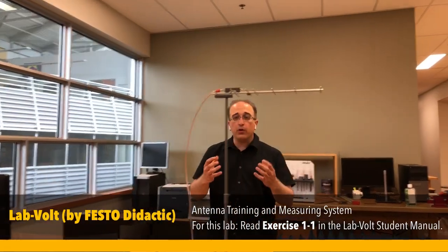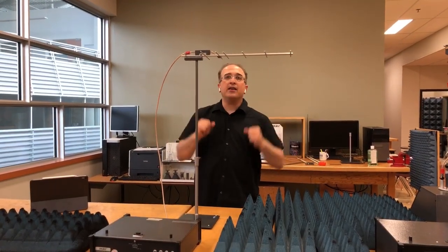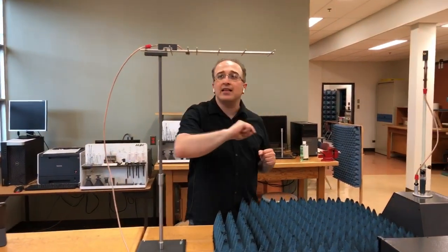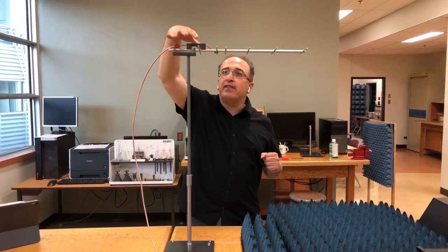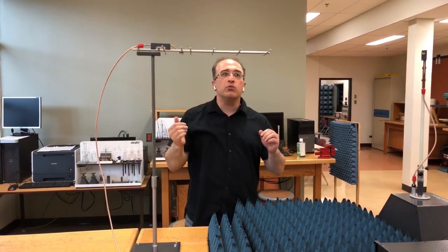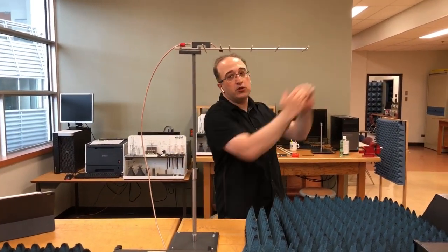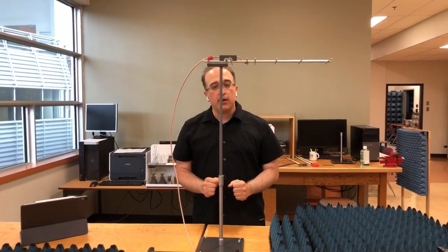It consists of 5 main components. The first component is this transmitting antenna. As you see, this is a Yagi-Uda antenna. It has 6 elements: the first, second, third, fourth, fifth, and sixth element. This is the active element. This is essentially fed, and the rest of them are passive. They are used to make the radiation pattern of this Yagi-Uda antenna more directive to this side. And this stand that we have for the transmitting antenna is stationary.